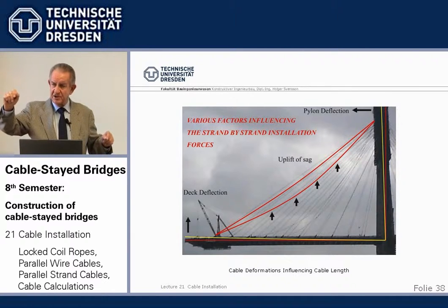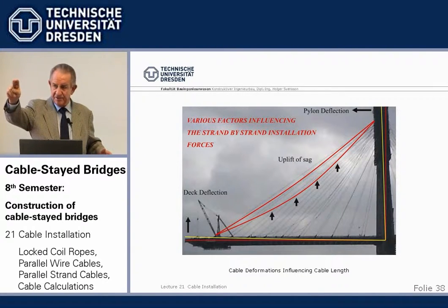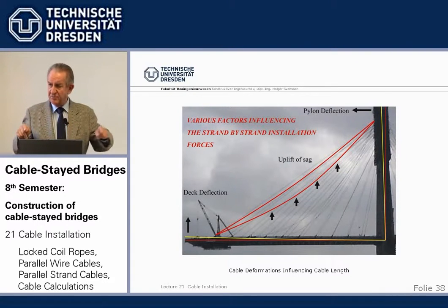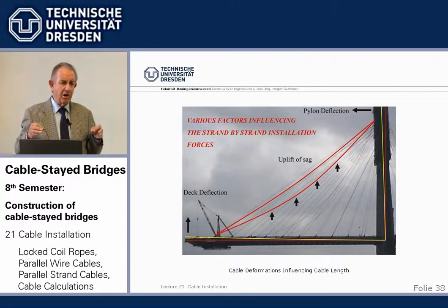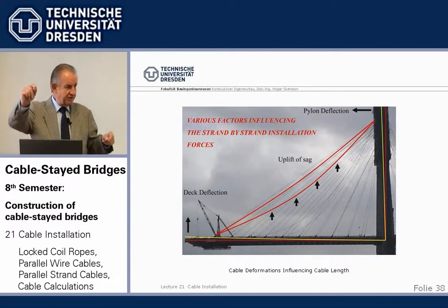When we have calculated that in this situation we need a shim-pack 4 inches, 10 centimeters thick, then that's all you need, because you know you have the correct cable length. And as long as the beam is built correctly and the tower head and all that is very carefully surveyed, you can't go wrong. You must come out with the right structure, because the cable length is predetermined.